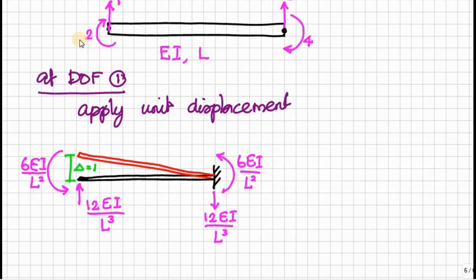We have 12EI by L cube, acting in the same direction as degree of freedom 1. Therefore, it is a positive force.